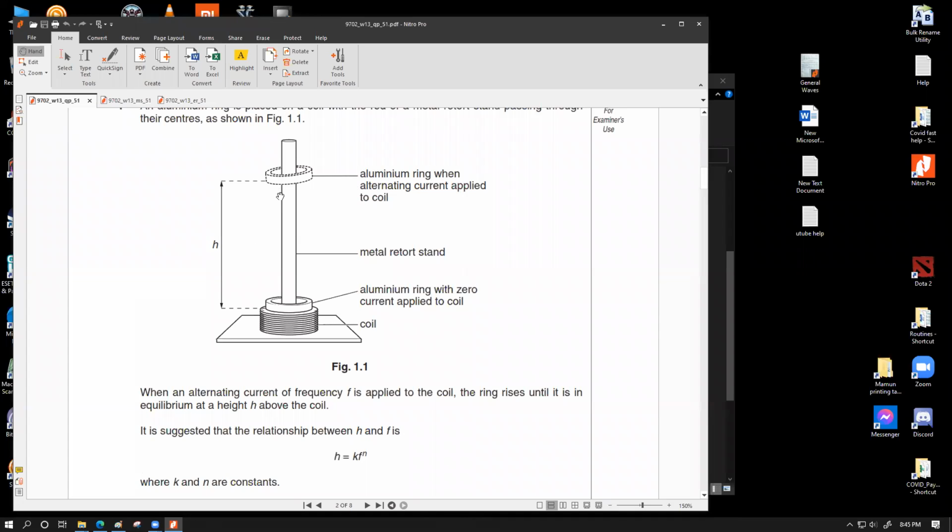I'll tell this again. Let's say you have this setup. You set up a strong light source in front of the setup, and place a screen right behind it. Whenever this thing is levitating, you will have the shadow of the whole setup cast on the screen behind the setup. Then you take the measurement of H from that shadow figure, so that you will not be disturbing the equilibrium of the metal ring while it is levitating. So that's actually a pretty convincing thing that we can go for. Yes, sure, why not? That can be one thing.